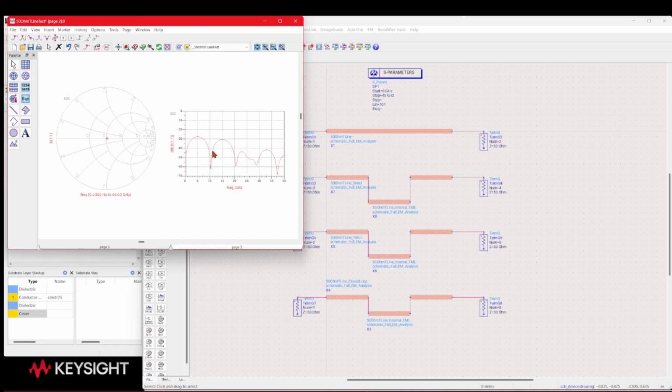With this kind of substrate it can go a bit over 40 gigahertz, but not much more. In this situation, as you see here, we stay very close to the center of the Smith chart, and this is the dB S11. I'd say we're around minus 30 dB. This is where we start from. This is our yardstick.